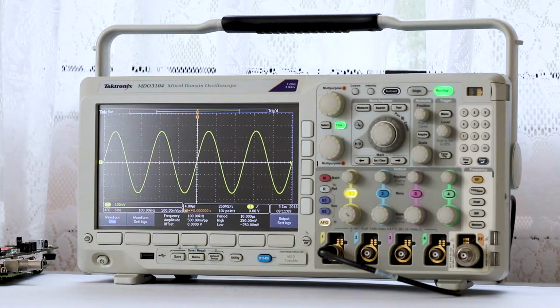The waveform, as placed in the oscilloscope's acquisition memory, is constructed according with various user-selected parameters. The sample interval is defined as the time between recorded sample points. This interval can be adjusted either by turning the horizontal scale knob or by pressing acquire and changing the record length in the acquire menu. Record length is a related metric. It is the number of samples required to fill a waveform record. The user can set record length by pressing the acquire button and using the lower and side menus.